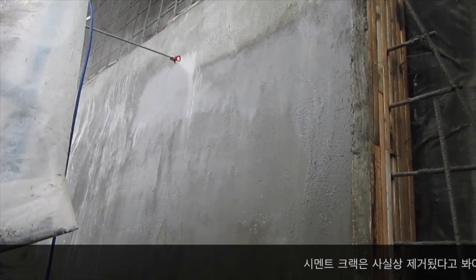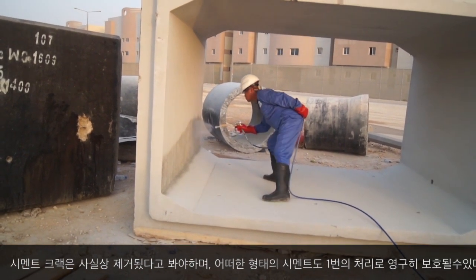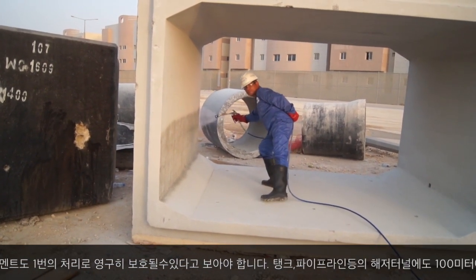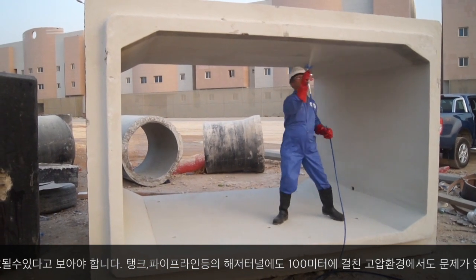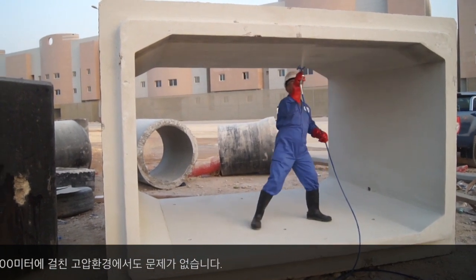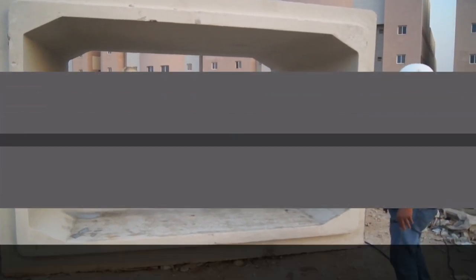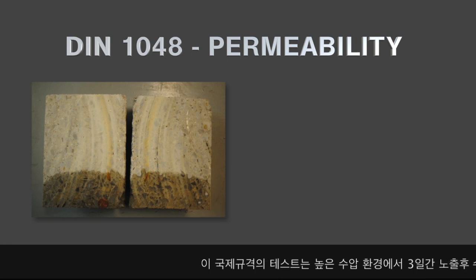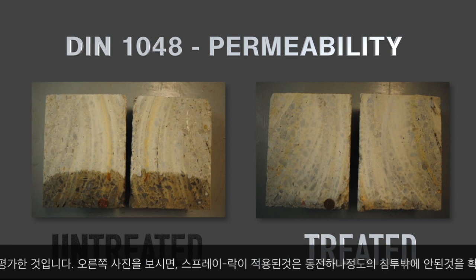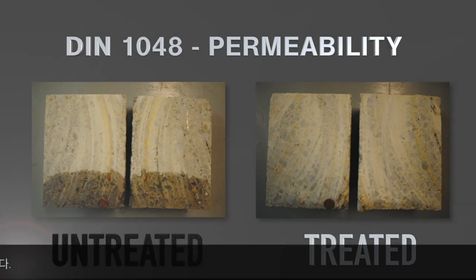All forms of Portland cement concrete can be treated by a single spray application in horizontal, vertical, or overhead concrete surfaces. One spray application from the negative or inside surface can ensure that underground tunnels, walls, tanks, and pipelines can be treated to prevent moisture damage to concrete. Spray-Lock has been used on walls where up to 100 meters of head pressure water exists on the opposite side. This internationally accepted test puts concrete under high pressure over 3 days to test resistance to water intrusion. Spray-Lock is added to the sample on the right, and you can see the very limited penetration by the size of the penny on it.